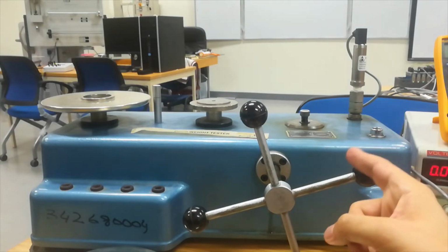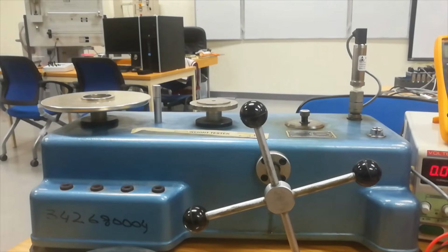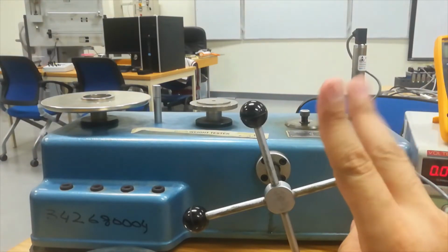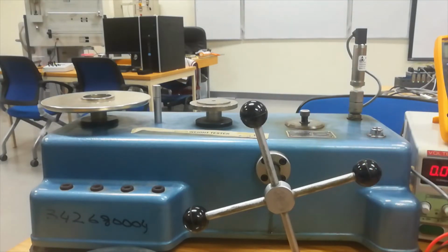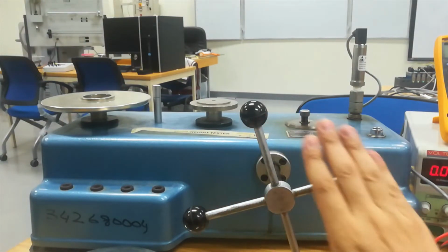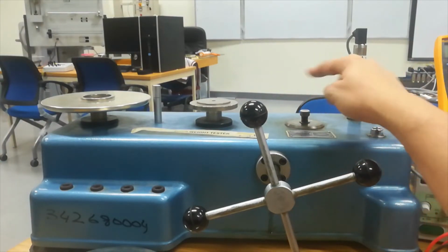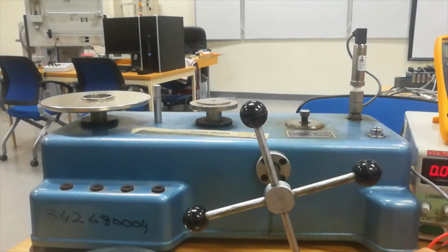And in order to make sure that there is no place for this oil to escape to, you need to trap the oil inside by doing two things. The first one is to open this valve. Once you open this valve, you are closing the path inside the tank, so there will not be any relief for the oil.